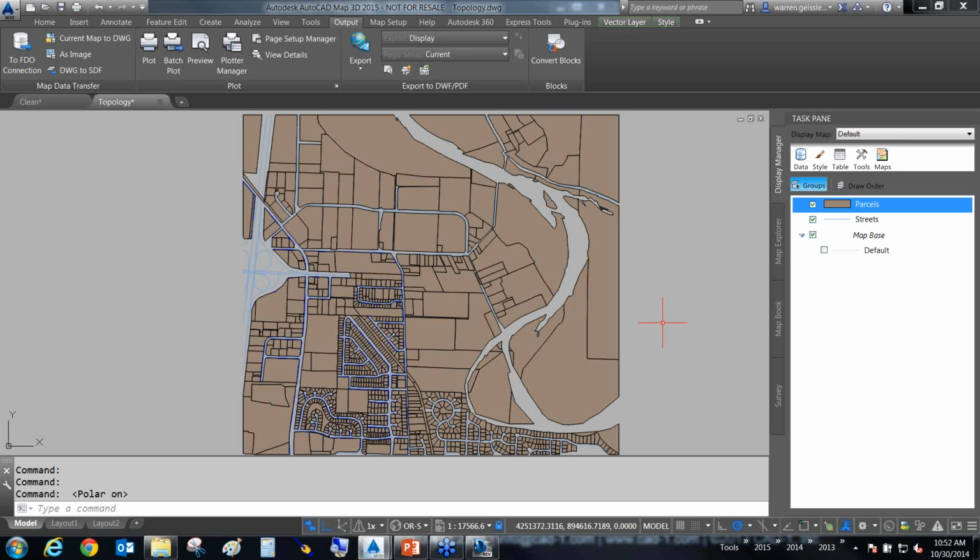Sometimes that port is a number, like 5151 is the default number that you'll use for the open port. Sometimes the port will have a name. As an example, Denver Water, they've opened up a port and they've given it a name, and you'll need to get that information from whoever your SDE administrator is. Quick word of warning for those people who want to connect to their Esri data, the people who are serving up the Esri data have to be using SDE with an open port. If they're doing what's called a direct connect, all of this kind of falls out the window. You can't connect using SDE because they're technically not using SDE.